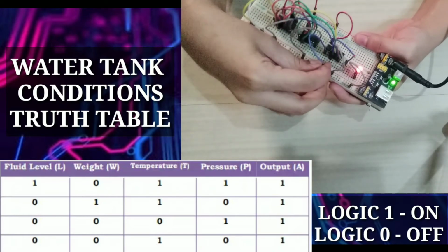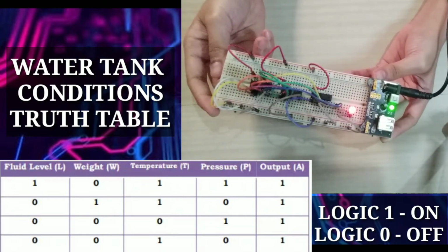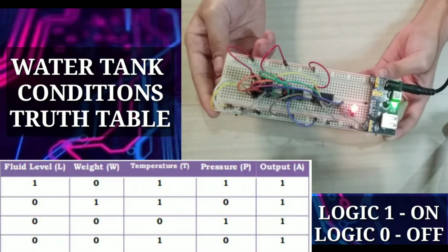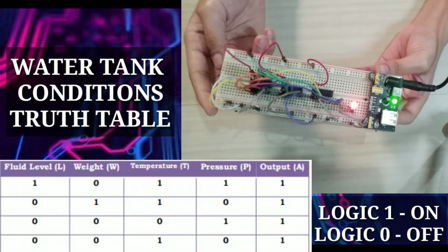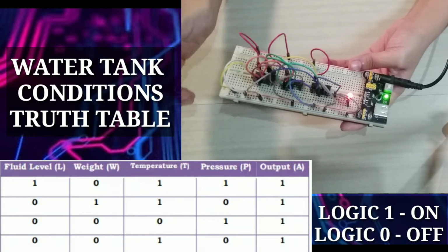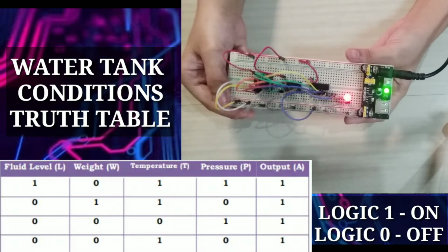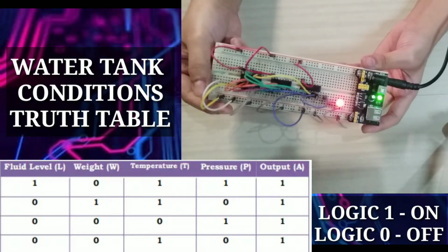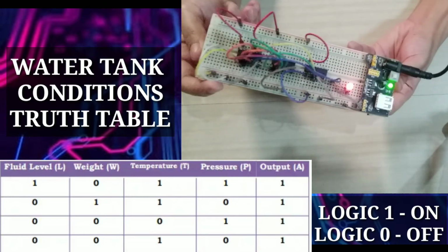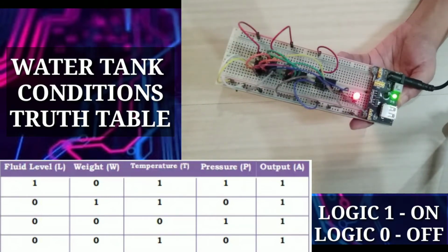And this one. As you can see, our LED lit up, meaning if the tank conditions are a high fluid level, a high temperature, and a high pressure, meaning all of the conditions are at logic 1, our output will be logic 1 as well. Or in the problem, if it's a buzzer, it will alarm or sound, and if it's an LED, it will turn on. So that's our output for the first condition.